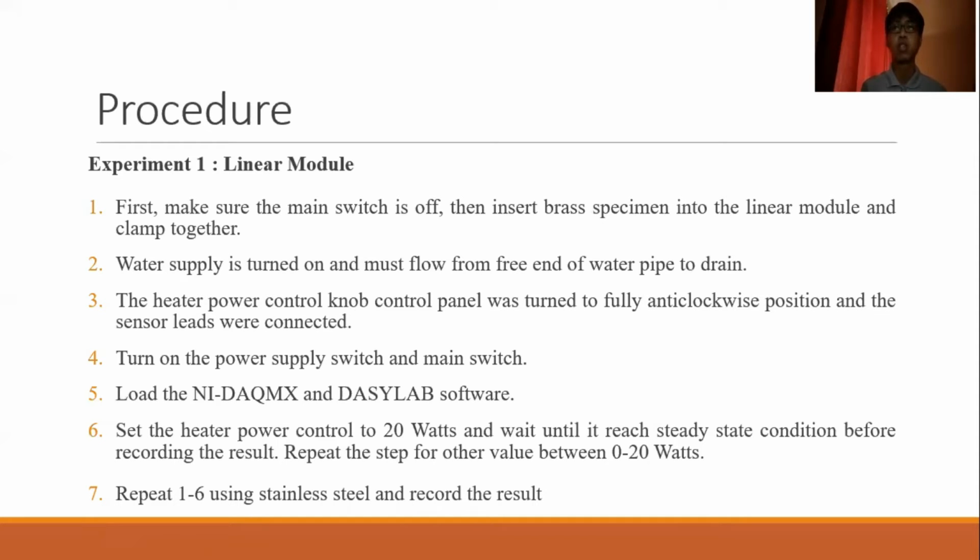Then we set the heater power control to 20 watts and wait until it reaches steady state condition before recording the result. Repeat the step for other values between 0 to 20 watts, and then repeat steps 1 to 6 using the stainless steel and record the result.